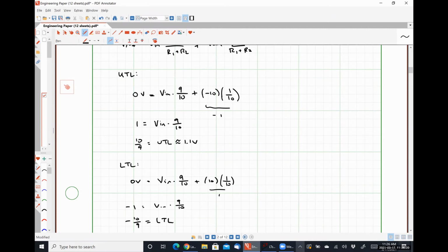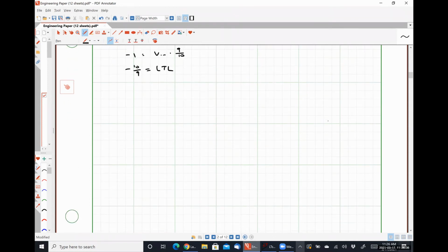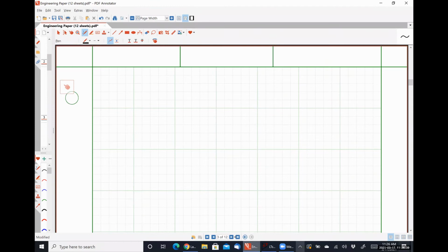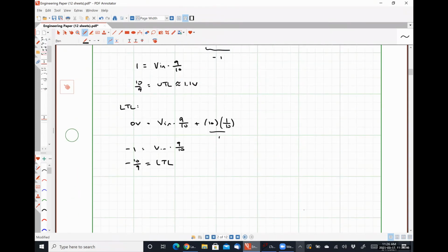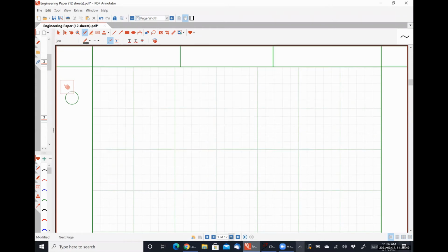All pretty straightforward. Again, this latching, having an upper trigger limit and a lower trigger limit, that's what's causing this thing not to ring or oscillate when we observe a noisy signal. So let's look at an inverting Schmitt trigger. So for an inverting Schmitt trigger, we are going to have something like this.